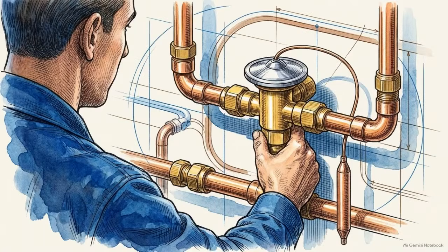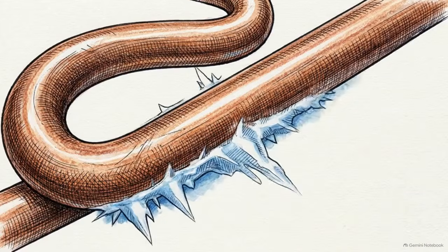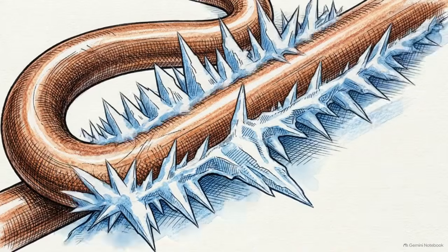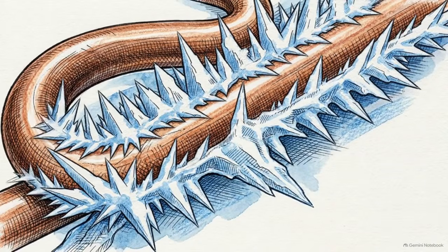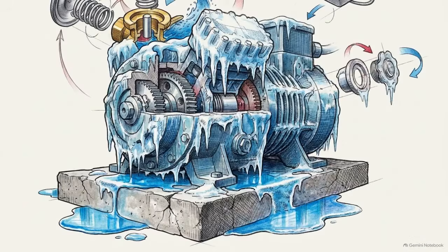When diagnosing a metering issue in the field, mechanical expansion valve failures generally manifest in 2 primary states: stuck closed or stuck open. A valve that is stuck closed starves the evaporator. Suction pressure drops, cooling capacity plummets, and the measured superheat registers abnormally high. A valve stuck too open floods the system. The superheat drops dangerously close to zero, suction conditions become unstable, and compressor damage is imminent.